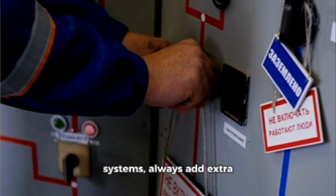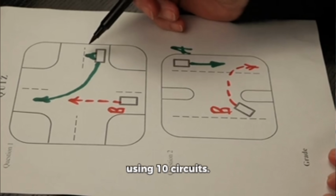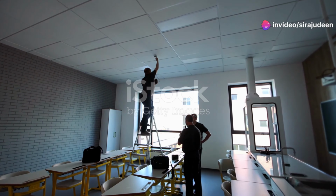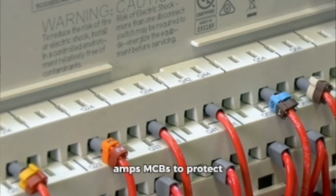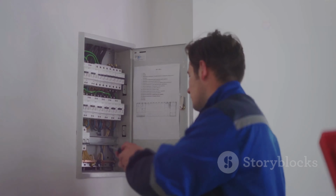When designing electrical systems, always add extra capacity for safety. For our lights, we're using 10 circuits, each rated for 500 watts, even though they won't use all that power. This extra capacity helps prevent problems and keeps everything running smoothly. We'll also use 10 amps MCBs to protect these circuits.